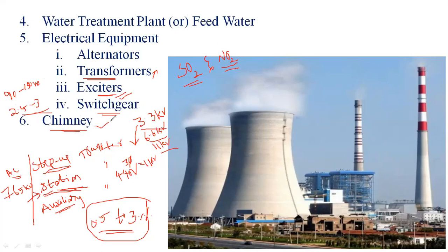Most power plants prefer the cement brick chimney, because the lifetime of a cement brick chimney is 50 years and the maintenance is also very little. If you go for the steel chimney, the lifetime is only 15 years, and maintenance is required. We need to apply regular painting.